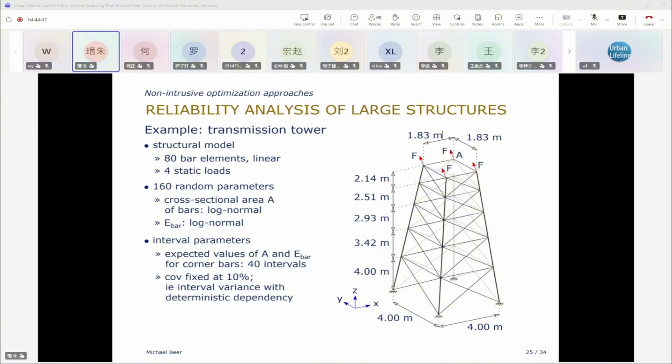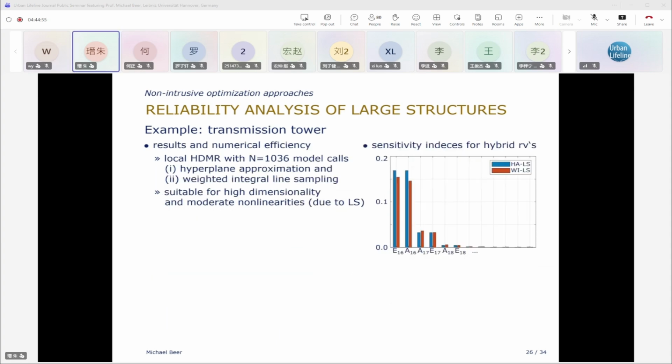So then we put the limit of 6 centimeters as a failure criterion. So first, we do a one-shot sampling, and then we estimate these terms for the high-dimensional model representation. These terms show the dependency of PF on one parameter at a time as the first-order terms, right?